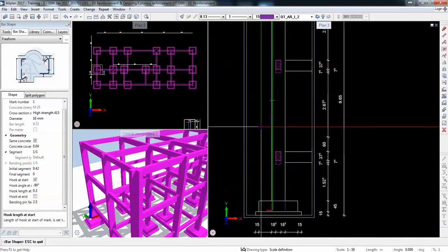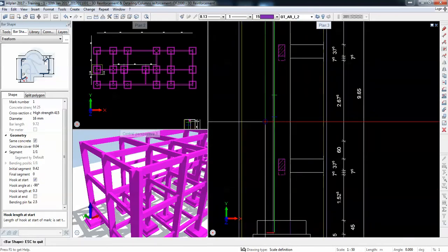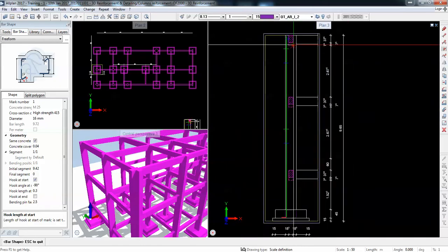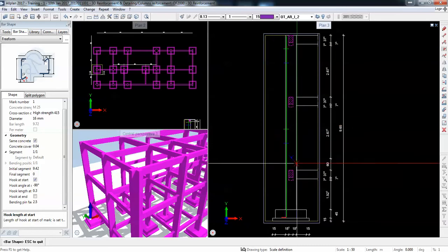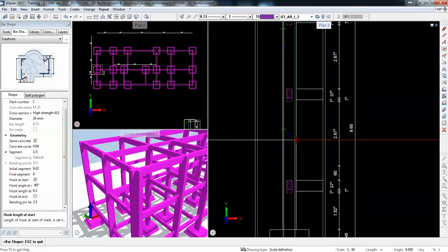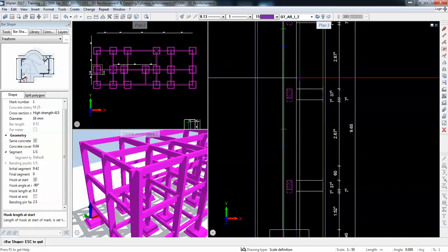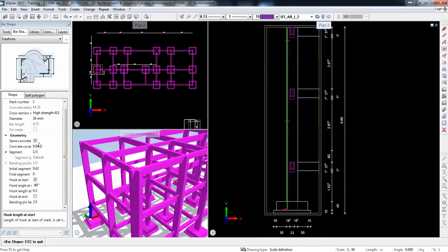Now what you're going to see here is the following. Because I inputted a smaller maximum longitudinal rebar, I have this proposed overlapping. Where we see the blue and the green line, in between we have overlapping, and we can control what happens in each segment of this overlap.